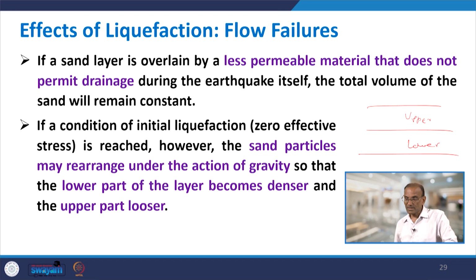So, what happens, the lower part could be denser, which is also expected, because the density of the soil may vary from the top to bottom, it increases, and the upper part will be subjected to this. So, the upper part may start the liquefaction, the initial flow failures.